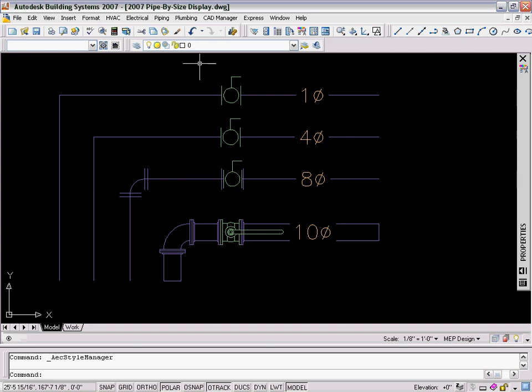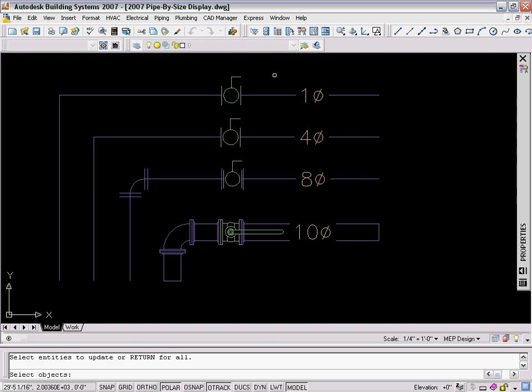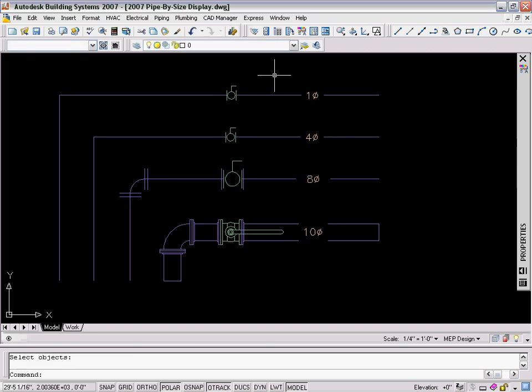So regardless of the scale that's set here, the actual size that's going to be used in graphical is going to be scaled accordingly, so that when you place a viewport with the corresponding scale, the plot length will be 1/8 of an inch. This can be illustrated by changing the scale here. So let's go ahead and change it to a 1/4 scale and regen the model.